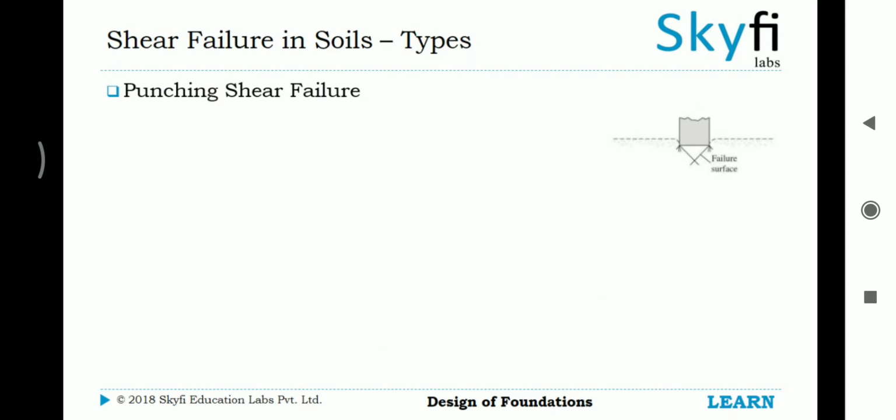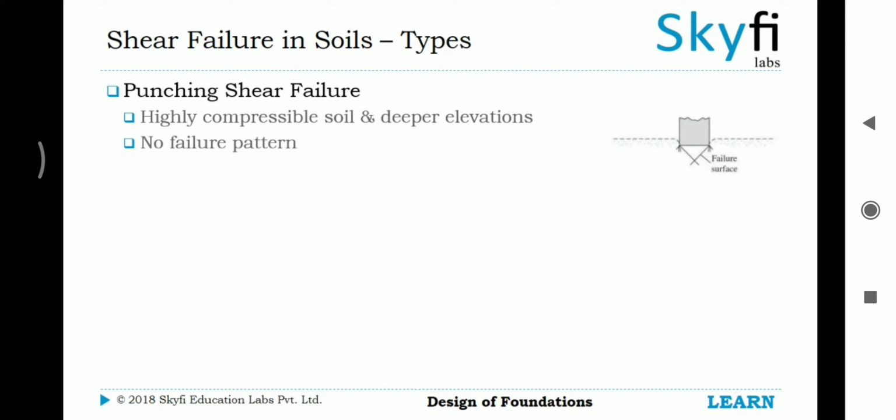The punching shear failure is seen in loose and soft soil, and at deeper elevations. There is no particular failure pattern observed. The soil doesn't bulge, but the footing undergoes settlement in this type of failure.